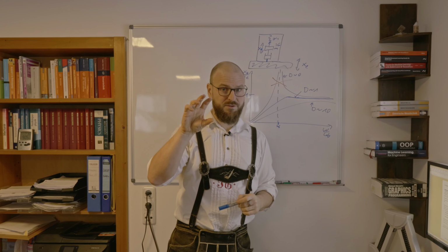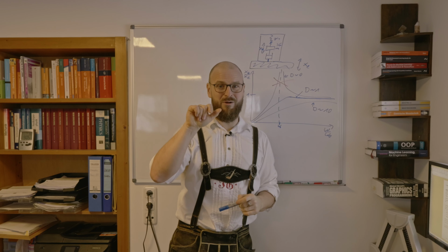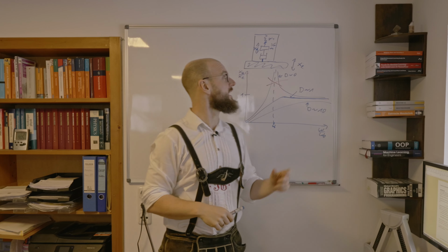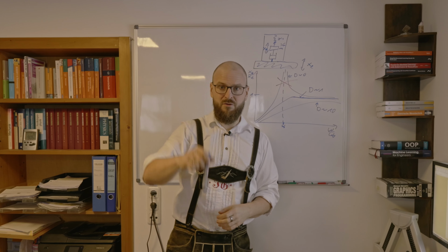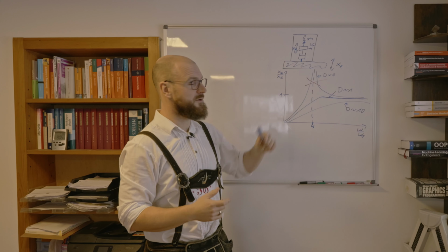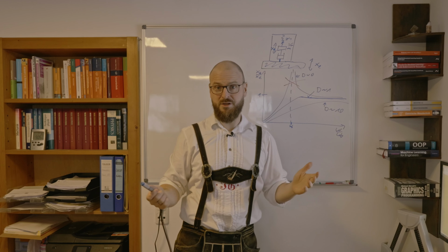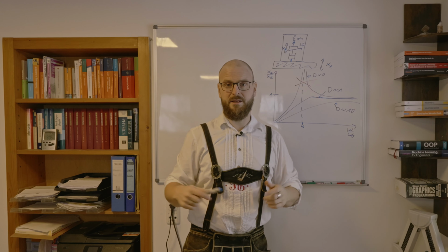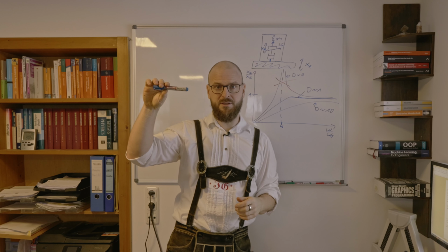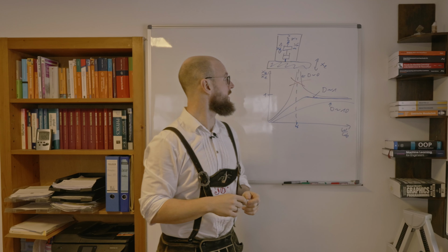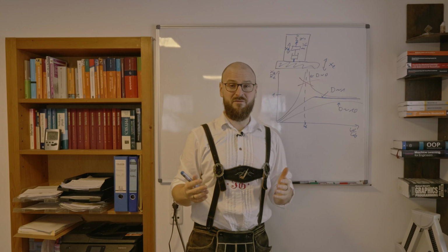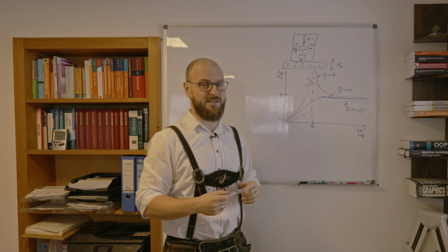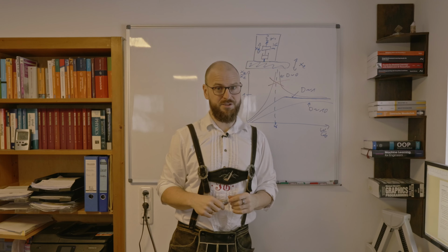Think of your mobile phones. You can turn them around and they will recognize if you're holding it straight up or you're holding it horizontally. That needs to measure the Earth acceleration. Can be done using inertial masses also, extending that system for a second direction and measuring the acceleration in X and Y direction, for example. And so on and so on. There are different, very manifold applications out there of measuring the acceleration or measuring vibrations.